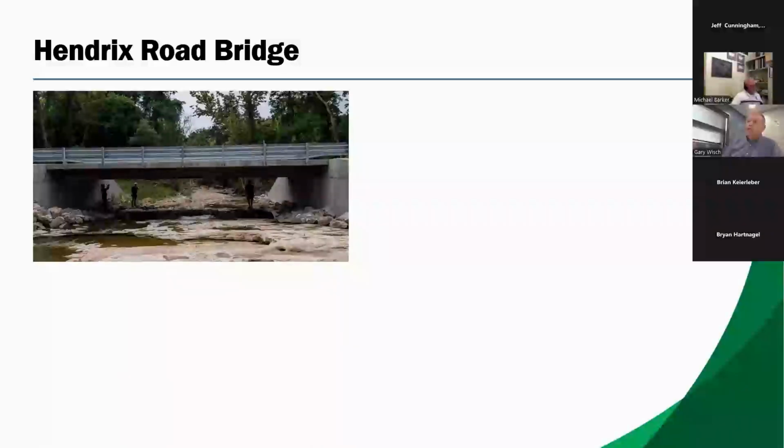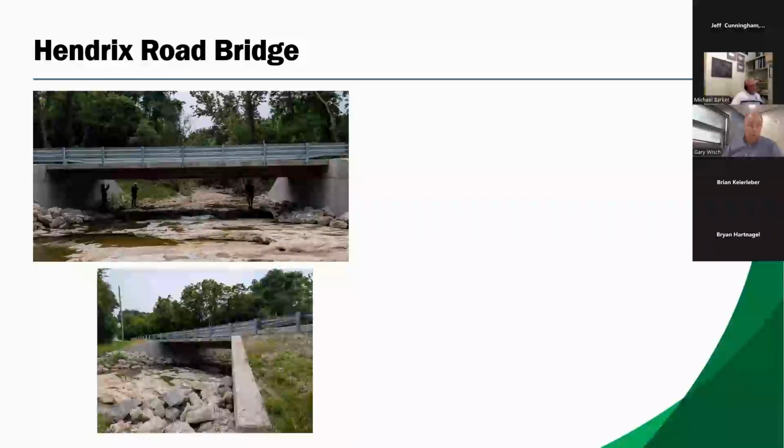So the next thing that we like about it is it's made with weathering steel. It doesn't require any coating. Now, we blast clean these beams to make sure that they would weather evenly. So a quick run through our wheelabrator to get an SP6 commercial blast finish, and these beams were finished. Is that the last Hendricks Road, Michael?